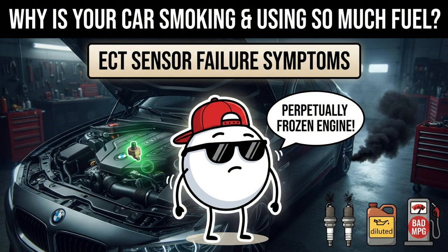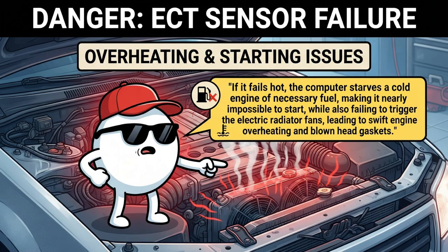It floods the cylinders with continuous excess fuel, leading to black tailpipe smoke, fouled spark plugs, fuel-diluted engine oil, and terrible fuel consumption. If it fails hot, the computer starves a cold engine of necessary fuel, making it nearly impossible to start, while also failing to trigger the electric radiator fans, leading to swift engine overheating and blown head gaskets.